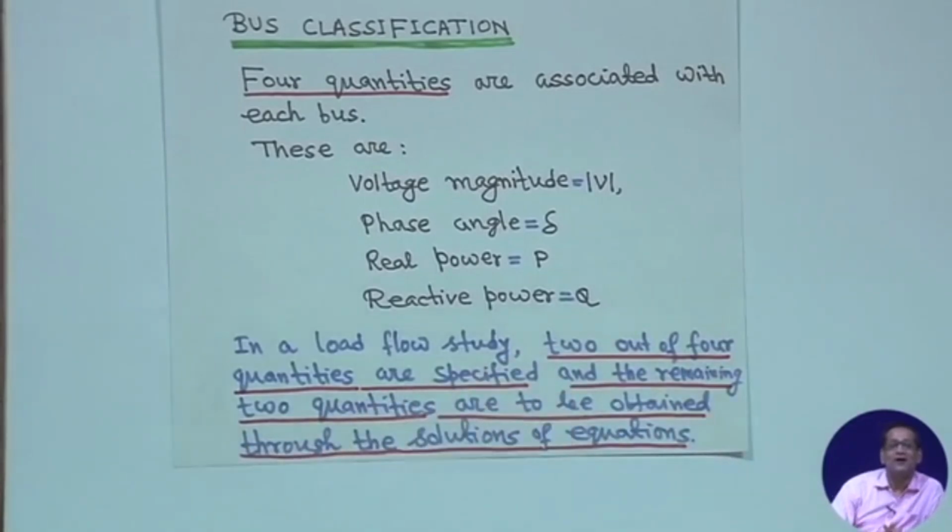Although at a third year level or even at PG level this may not be very familiar to you, take the case when a distribution network is working in islanded mode, that is, it is not connected to the grid. At that time you will find load flow is completely different. Particularly for dispatchable DGs like biomass DG or diesel generator, one has to consider the droop characteristics.